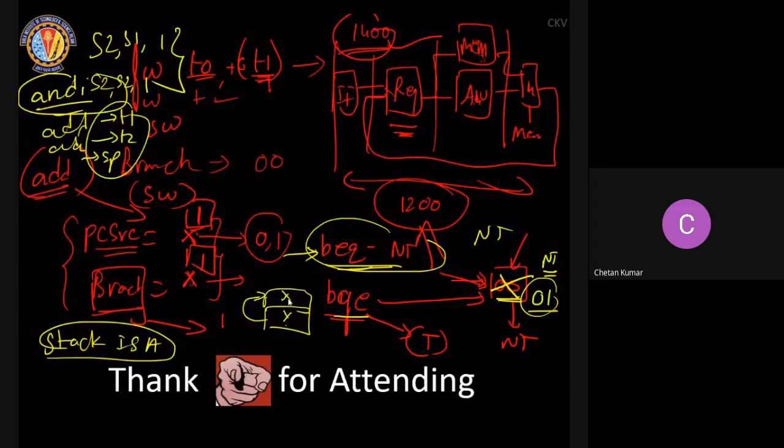by sending the entire instruction code along the pipeline. You can, technically you can, but the pipeline register size will be unnecessarily high. Instead of sending just 4 bits, if you want to send a 6-bit opcode plus function codes, you can still send, but that is an unnecessary usage of resources.